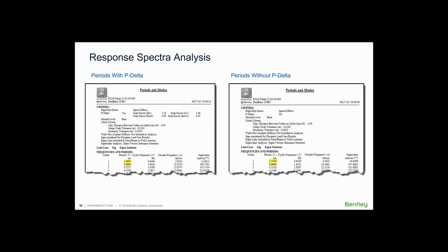The fundamental mode in the x direction is 1.5897. So that's the first mode's period, which is the one that's typically the dominant one. So when we're looking at equivalent lateral force, that's the period we're using. It's from the first mode. It's not some average of all of them. We wouldn't take the average of all of them and use that average number.